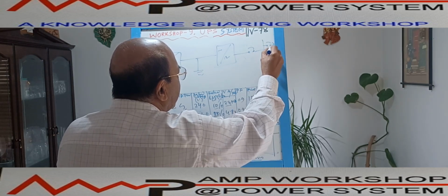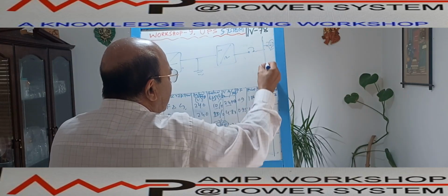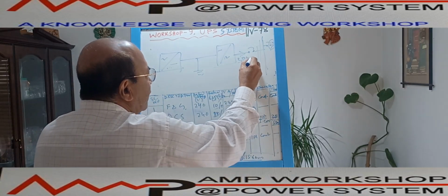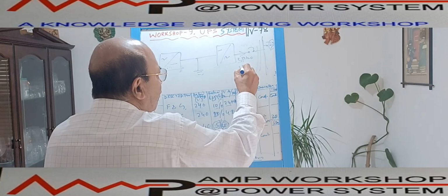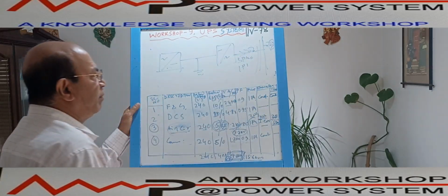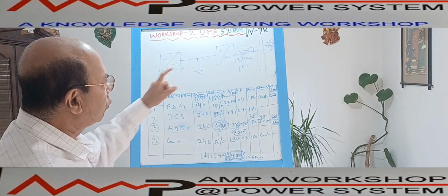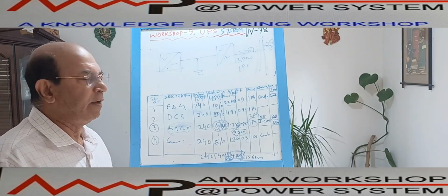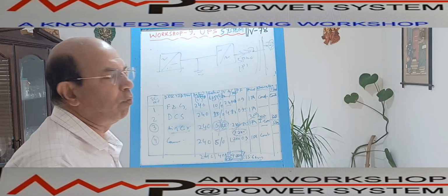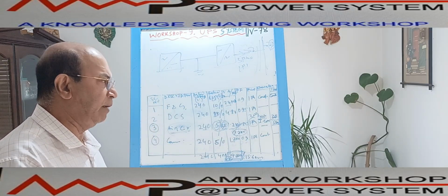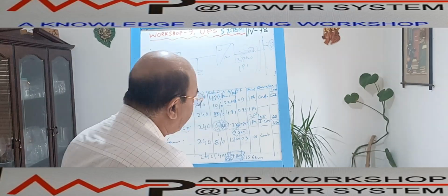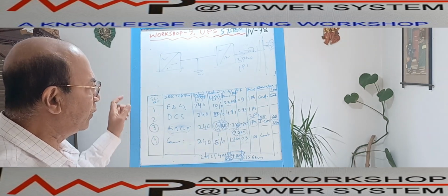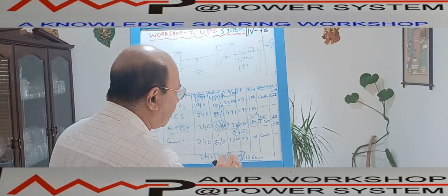This is our configuration. Now, if this load is 3-phase, that means I need a 3-phase bus over here. That means this UPS needs to give 3-phase output, right? But if all the loads are single phase, then I need the UPS output to be single phase. Inputs could be anything. So that's why to decide the UPS output voltage, it is very, very important to know the load phases. Is it a single phase load or three phase load? If the loads are all single phase, the output of the UPS will obviously be single phase. But the question is, what is the total kVA requirement?